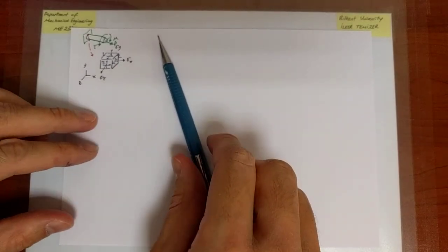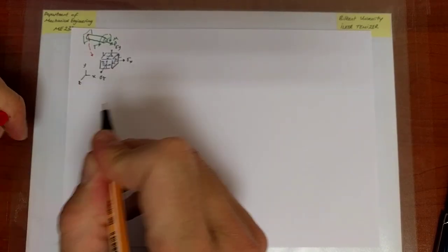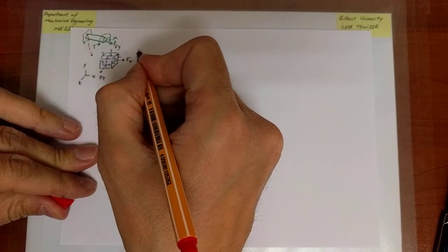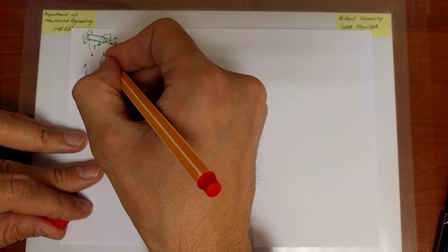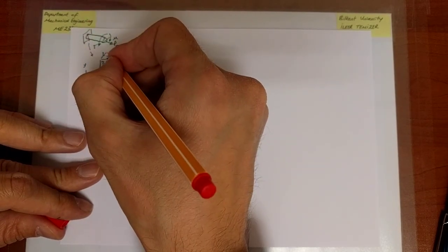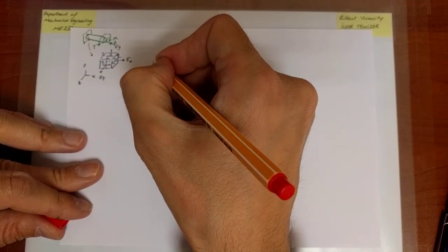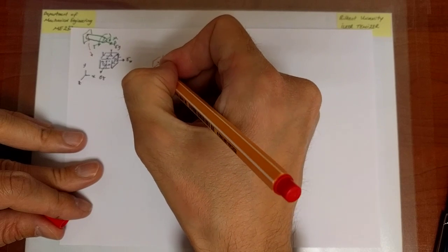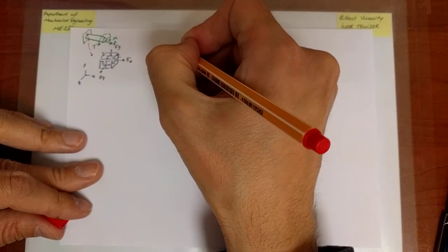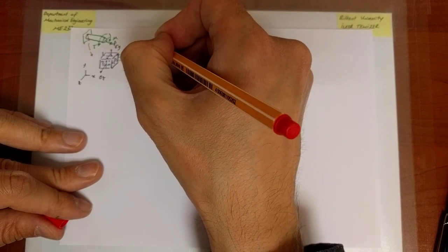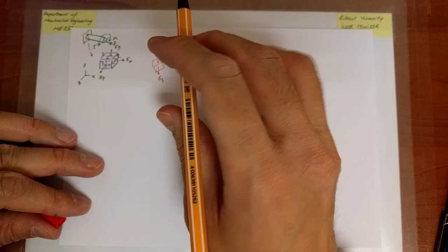Now, what we have learned from our discussions associated with principal stresses is that I can convert this picture to the principal picture. So in other words, I can represent the state of stress at the same point with a cube that is oriented along the principal directions and along which there are normal stresses sigma 1, sigma 2, and sigma 3.